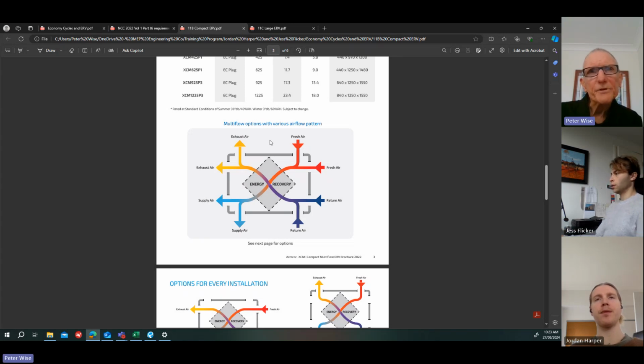Because that table says if it's 200 litres a second, they only need to be a metre apart, even if it's toilet exhaust. So that applies. But I think what I'm trying to say is if it's 1,000 litres a second or more, 1668 Part 2 says 6 metres, but if you can't achieve it, it's not critical with this type of system.